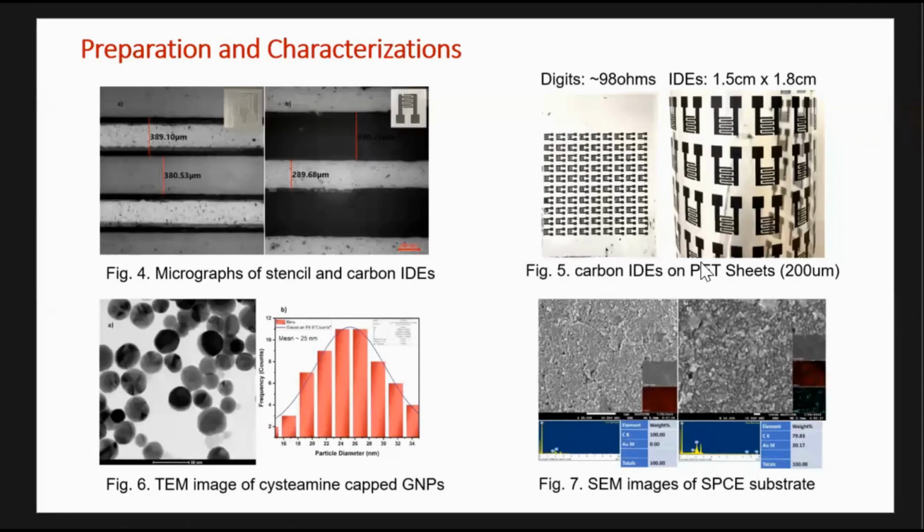At a time, for an A4 sheet of 100 micron PET sheet, you can squeeze in and get 90 sensors. Of the 90 sensors, 20 will be lost, so 70 you will get. And these are thin sensors. For transportation, like a printer bunch, you can put a thin paper above each sensor pad and bunch it, or you can roll it a little bit. Obviously, the diameter has to be a little big, so the space is less, and you can transport this sensor. So this is the upper substrate fabrication.